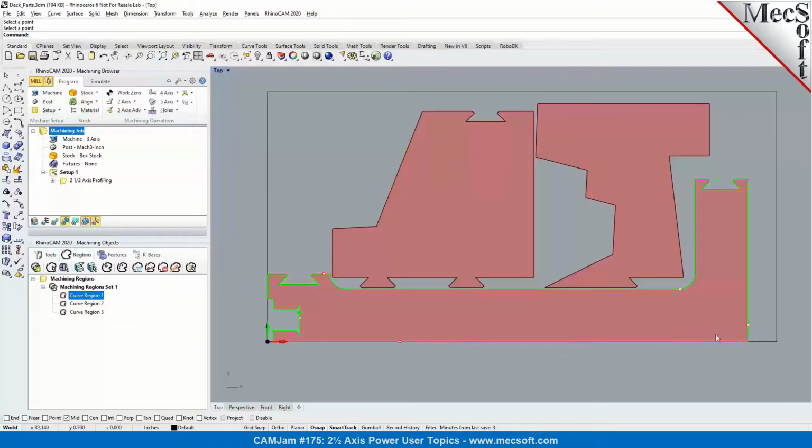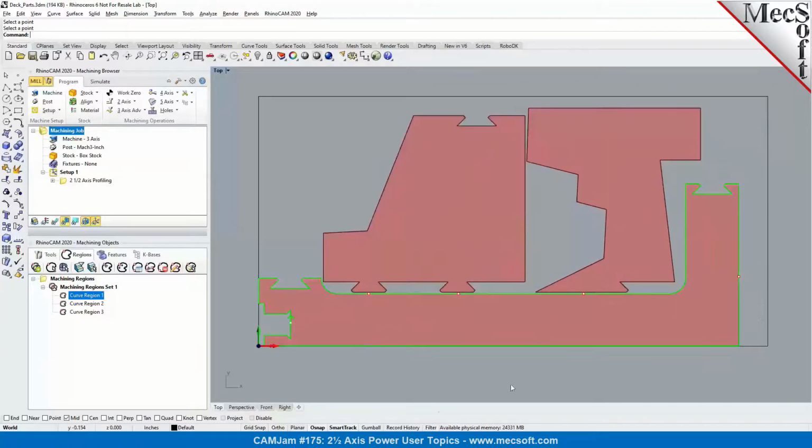Once you create the bridge points, you could also move them. I can just double click, or I can single click on it and move each of the bridge points. I could say I would like to take this bridge point and move it closer to this location. Rather than having to click on it each time, I can double click to edit so it stays modal, and I can keep moving multiple bridge points. I can take this one here and move it right over here. Then once I've finished moving the bridge points, I can right click or press enter to accept it.